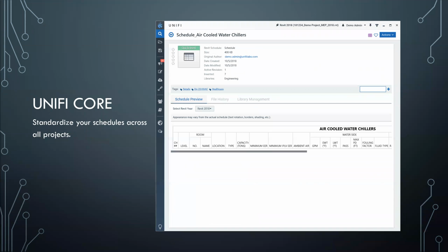And in addition to giving our users the ability to review that parametric data of each piece of content within their library, we can also provide workflows that help your team load the appropriate data standards into their project. Now, this is helpful because in multi-discipline engineering firms, in order for this information to talk to each other in the form of data, they'll need to use a common set of shared parameters. Now, again, this is specific to Revit, but if you're not using the same shared parameters, the data set is not technically the same data set. So here you can see on this screen, here's one way that we're providing value to those multidisciplinary engineering firms by giving you the ability to store these schedules in your library alongside the rest of your content. Because what happens here is once you insert this schedule into your project, along with that schedule comes all of those shared parameters. In other words, you're creating a data standard here that you're now able to import into your project.